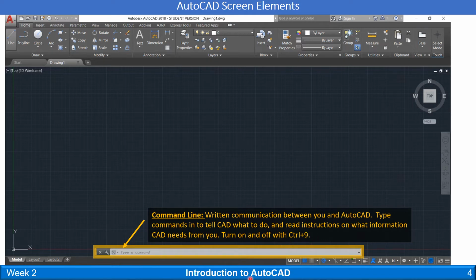This is the old-fashioned way of entering commands, and it's almost like a programming language. You have to know what to type in for lines and circles. It's pretty straightforward. Rectangle is REC, and there's all these little shortcuts, but all of the older people who are using CAD, they'll use the command line. I think the command line is really the faster way to do it still, but you have to learn the shortcuts and the coding for everything. But this is how AutoCAD's going to communicate.